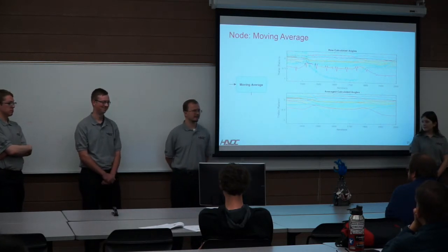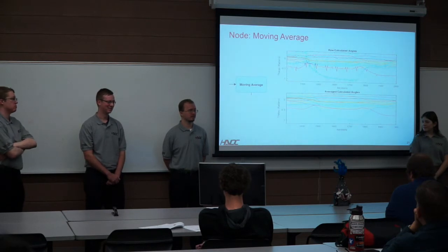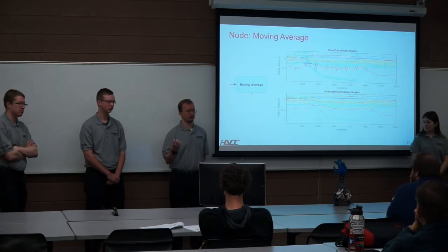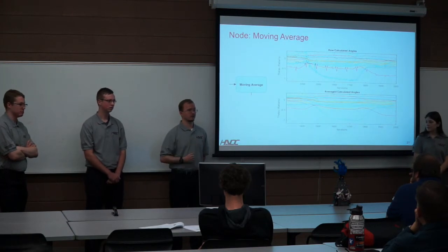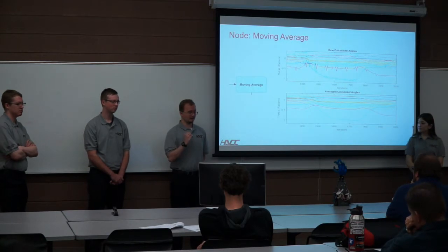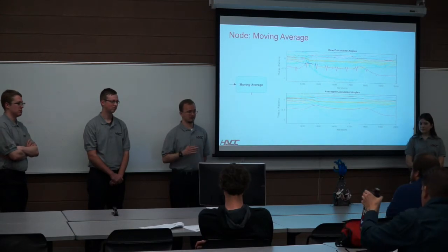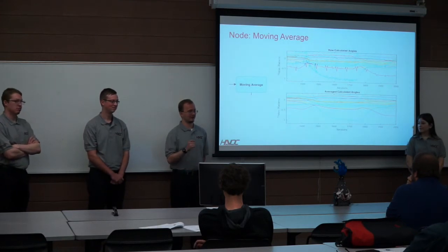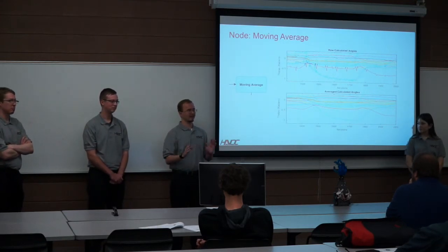The change I probably would have told myself earlier in the prelim semester is that, as I mentioned earlier, we switched from following the end effectors of the operator's hand to following the direct joints. The reason is that we found partway through that the math behind trying to follow strictly the end effectors is much more complex and much more unreliable than just following the joint angles and using the robotic kinematic equations that I presented earlier. This would have saved quite a bit of time, and the long nights of trying to hash out what equations could find the angles between a knuckle and a fingertip and actually make it look realistic.